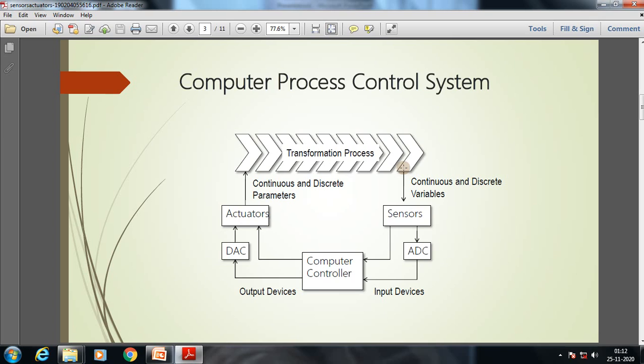Suppose we apply pressure to one segment of the Rochelle salt, and in another segment there is a change of shape. Any such change in these materials creates a specific voltage difference. If we connect to that voltage difference, we get a voltage signal according to the changes in the input material.